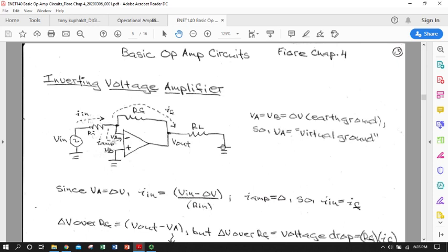Just as a note, one of the reasons that I like to write a lot of ground references rather than just showing maybe a floating reference, if I know that a signal is ultimately referenced to ground, or that an output is going to flow through some network to ground, I like to show that because I like to remind myself where my ultimate zero reference point is.